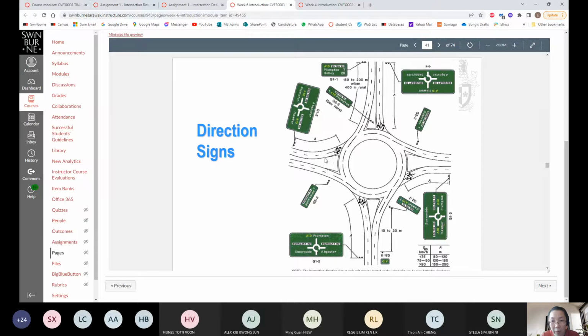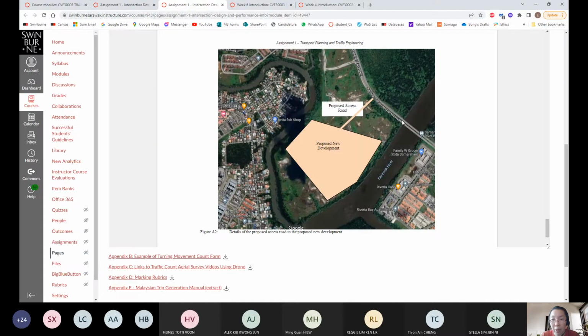So at the end of the day, after you've completed task 4, this is the outcome that we will see. For task 4, it's basically a drawing complete with line marking and signs. What we get is something like this. You see this is a splitter island that continues with a median. As you approach this, there is a median here. If you want, you can widen the median a bit, that's fine. Then your roundabout is here, and then you have the splitter island and it goes back to a 4-lane two-way with a median.